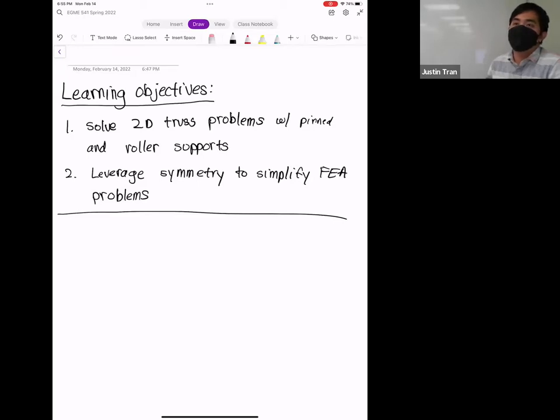2B is a bit confusing in terms of how to compute. I set it up, I actually want to talk to you about it after. I'm talking about how to set up the stiffness matrices when you have to combine a truss and a spring. Oh, for sure, you literally just combine them where the nodes are overlapping. When they overlap, you just add them together.